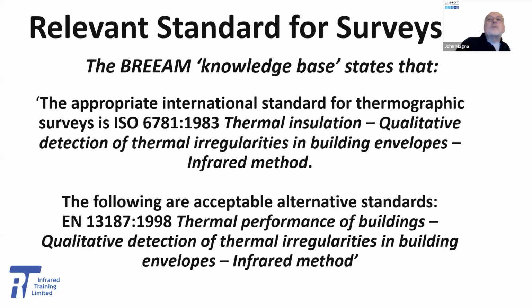It'll mean that thermographers will need to develop working relationships with air tightness testing companies or have access to their own fan equipment. It isn't really practical to carry out thermography on a building at the same time as the air permeability test, as the 10 degrees Celsius delta T minimum required for the thermography would typically cause a static pressure issue for the validity of the pressure test.